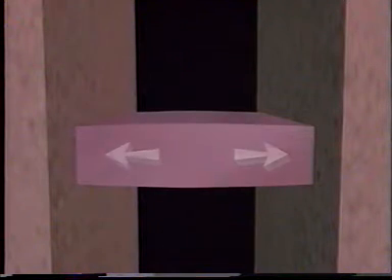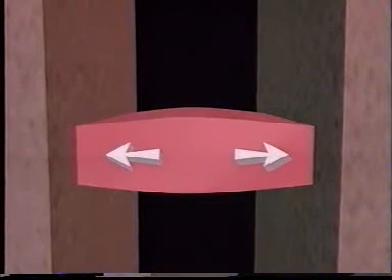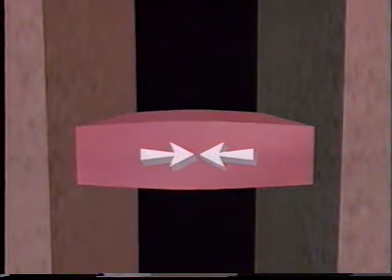The basic problem with welding and other methods involving localized heating is that metals generally expand when heated and contract when cooled. If they are free to expand and contract without restraint, residual stresses would not be generated. But if both heat and restraint are present, residual stresses are formed. This is what happens in welding. The metal is locally heated and restrained by the metal next to it that remains cool and strong.